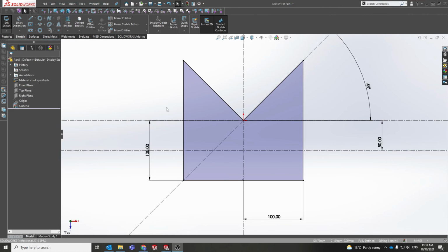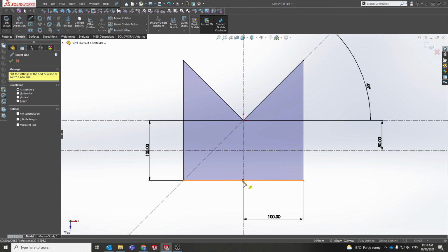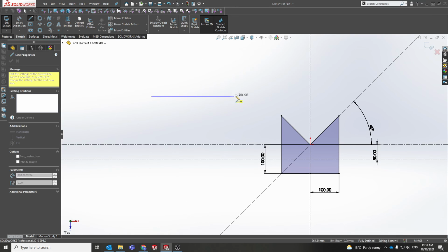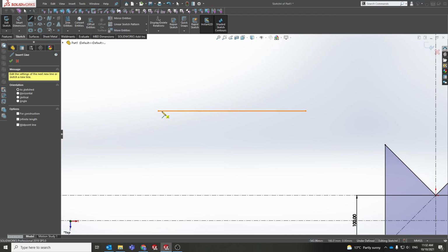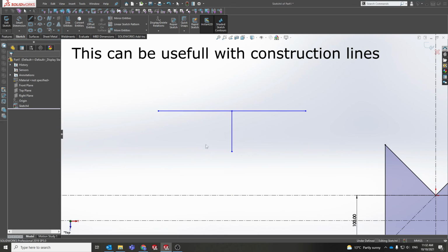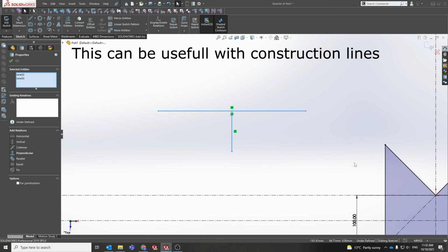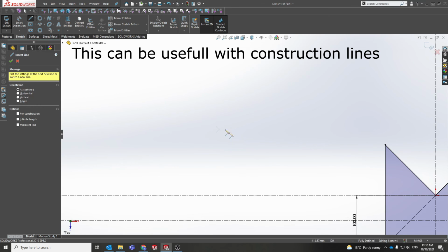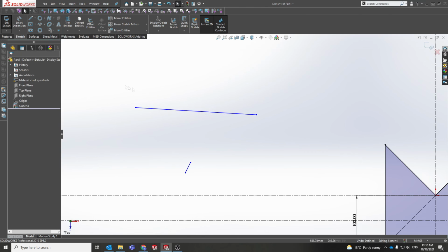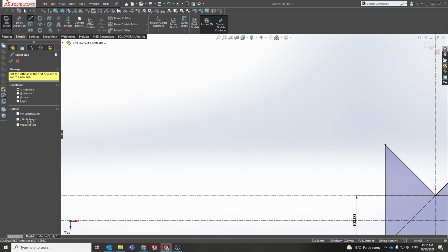Another tool which I almost forgot to mention is using midpoints. Midpoints normally snap anyway, right? So if I sit on this line for long enough, it will show me that's where the midpoint is. So I'll bring an example over here. If I draw a line, I can snap to that midpoint fairly easily, which is kind of handy. If you're struggling to find it, you can also go, you got your line there, line coming in here. Hang on, let's maybe make some square things happen.